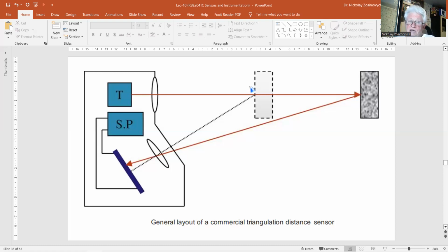The resolution is typically one order of magnitude better. Besides simple distance measurements, the principle is also applicable for range finding and imaging. Such systems comprise a rotating scanning mirror for one-dimensional or two-dimensional scanning of reflecting objects.